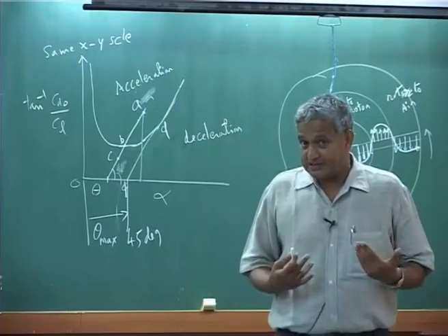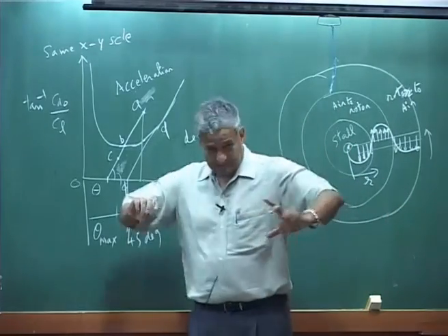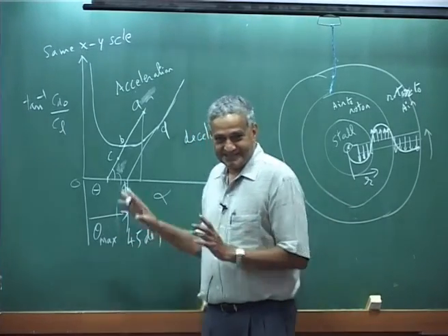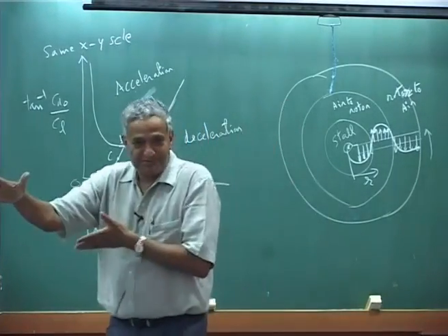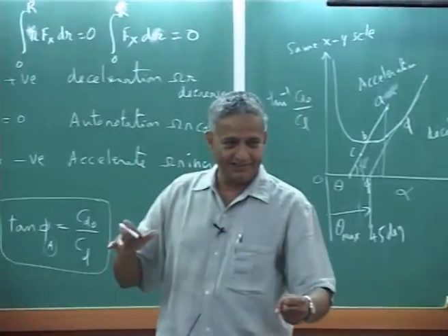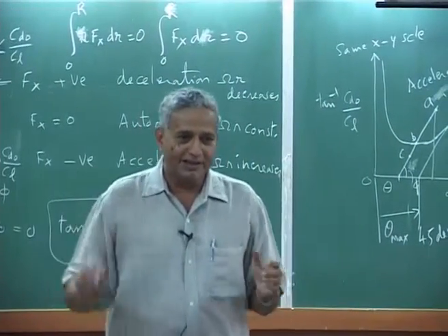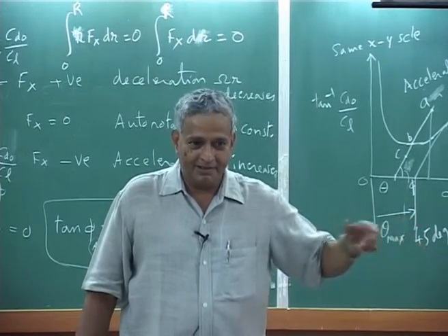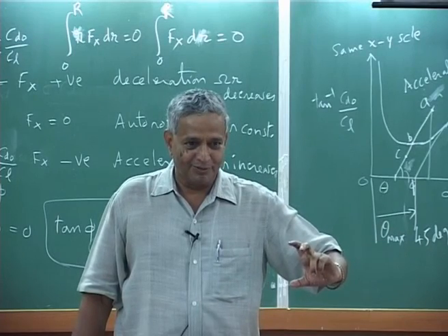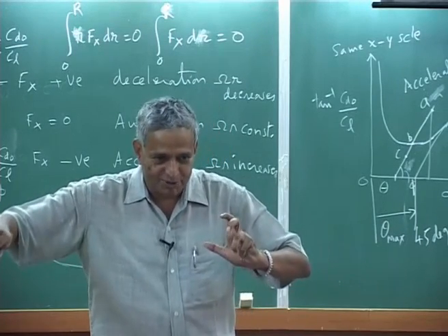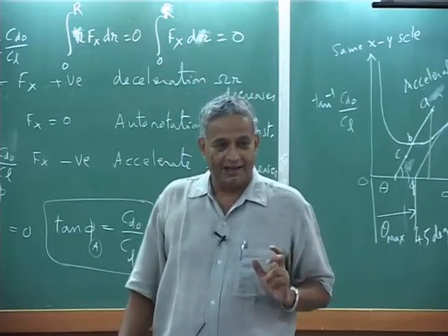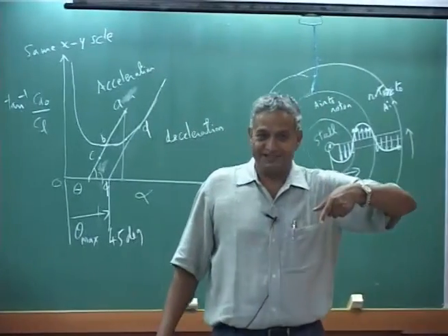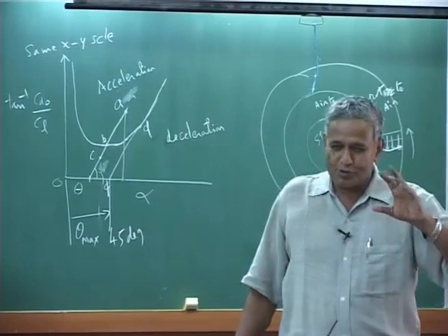But here, please understand, we have not considered the elastic twist of the blade, nothing is considered. This is like a rigid blade because I keep a pitch angle and then only the inflow angle is taken. You follow? But in real life, it is not just the inflow alone. You are going to have even elastic twist of the blade, and then you will also have blade flapping. Please understand, that will also give a velocity. So it's a more complex thing.